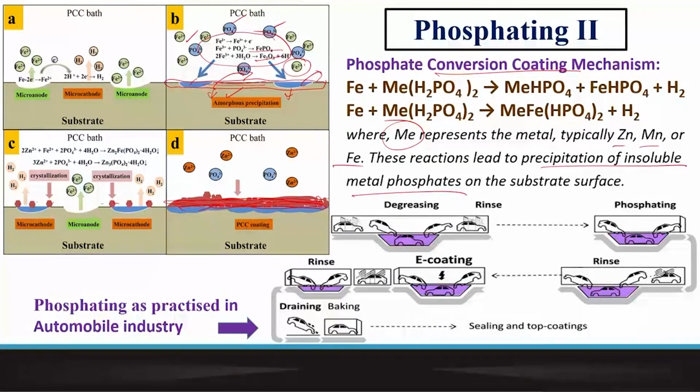If we control well, the surface contour could be fairly smooth, or in other words, we can reduce the amount of porosity in it. But again, I would repeat, the main attractive proposition here, the reason why this is a very desired process, is the high adhesion of the compound layer that forms.